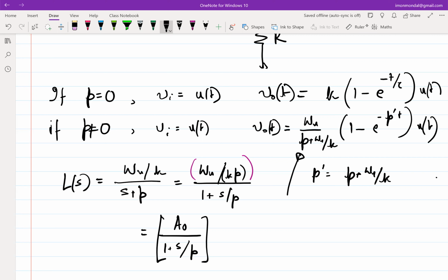Okay. So now things become slightly interesting here, because if you look carefully, there are two things happening. One is something is happening at omega U over K. Why is it constant till it almost behaves like the ideal scenario that we expect, till omega U over K? And what is omega U over K? It's the point where you are hitting the 0 dB line. So that's why this omega U over K is often called the unity gain bandwidth of the loop. In this particular configuration, omega U over K we call the unity gain bandwidth, or in this case, we will call it omega U loop, because it's the unity gain bandwidth of the loop.